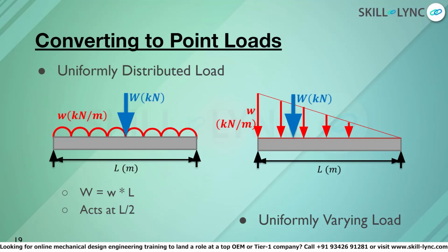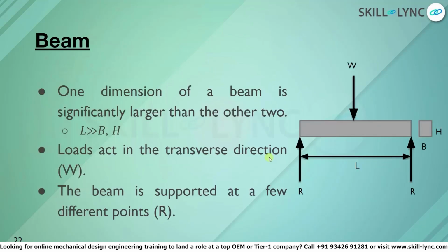It can be straight or curved. It can be homogeneous or composite. That is, it can be either made of the same material or a composite of two materials. A beam can have a constant cross section or be tapered. A simplified beam for ease of calculation is considered to be straight. Also, it is assumed that the deformation of the beam will be in the linear elastic zone of the stress strain curve. We will also assume that any deflection due to loading will be small.